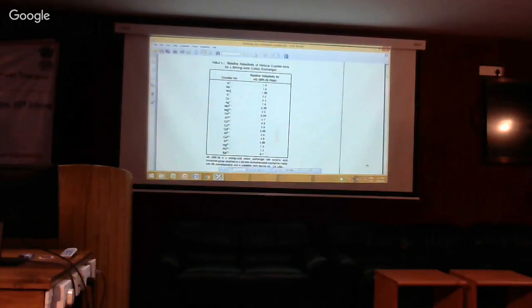Okay, so the point that I'm trying to make is that this resin, strong acid cation exchanger with sulfonic acid functional group, will not be suitable to remove zinc or cadmium or copper or cobalt or nickel, because it doesn't have the selectivity. Why doesn't it have the selectivity?